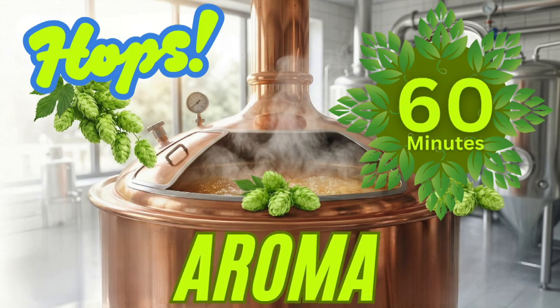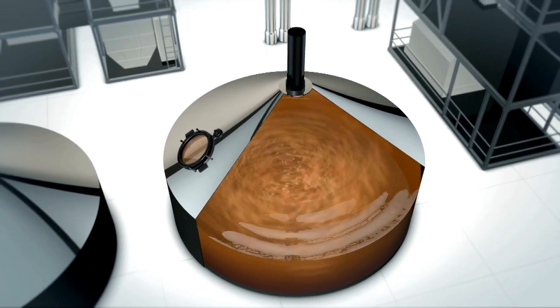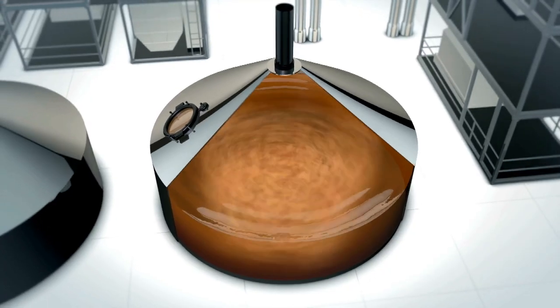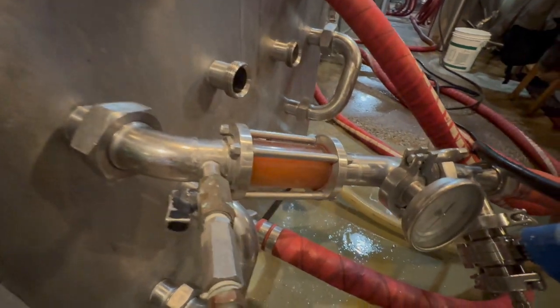After the boil, the brewers create a whirlpool in the kettle. This helps separate the hops and other solids from the wort. As the whirlpool spins, the solids collect in a cone in the middle, letting the brewers drain the clear, aromatic wort from the side.